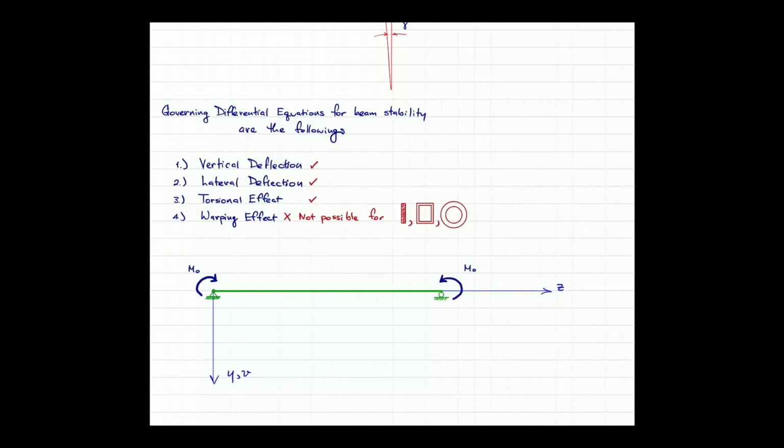The reason why the derivation is carried out in this picture in this way, having just the applied moment like this, if you draw the bending moment diagram, you find something pretty much like this. So you have just the constant moment throughout, and you do not have shear. The shear force diagram turns out to be just 0.